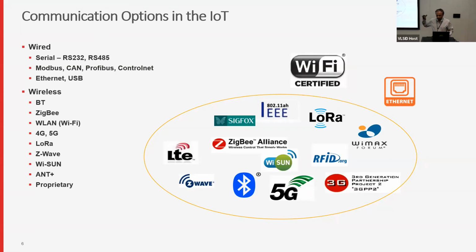And because of all of those rules, you cannot have one size fitting all. Just like you have cellular, whether you're using it for video or voice or anything else, the same protocol is used, with some variation of course. Here it's all different. Very short range like RFID, you go very close to a door, or you drive your car to the FASTag toll gate, then it opens. Short range communication. Then you have longer range communication also needed, maybe at 1 or 2 kilometers. IoT doesn't have hundreds of kilometers. You don't have satellite links. Satellite links are all licensed spectrum. So a few centimeters to a few kilometers is what the range is, and each of them gives differently.